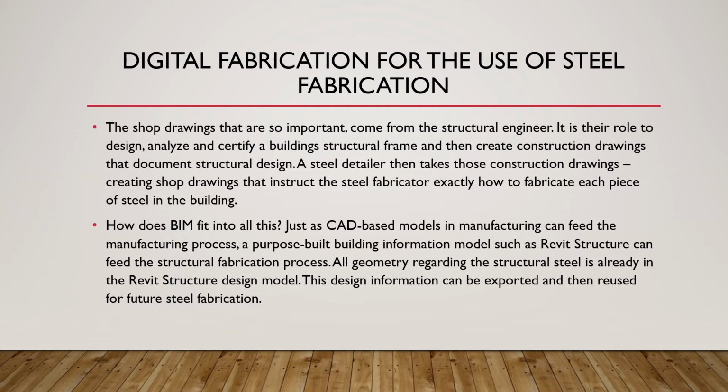How does BIM fit into all this? Just as CAD-based models in manufacturing can feed the manufacturing process, a purpose-built building information model such as Revit Structure can feed the structural fabrication process. All geometry regarding the structural steel is already in the Revit Structure design model. This design information can be exported and then reused for future steel fabrication.